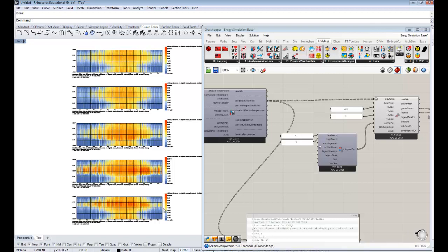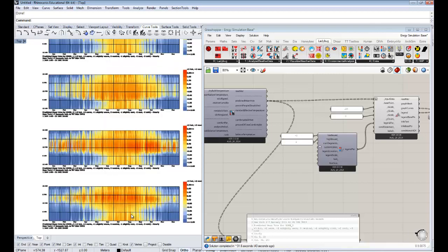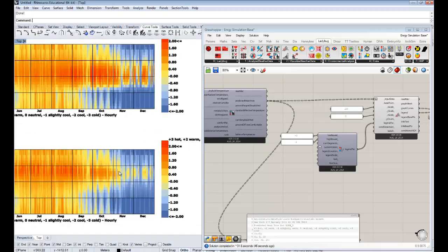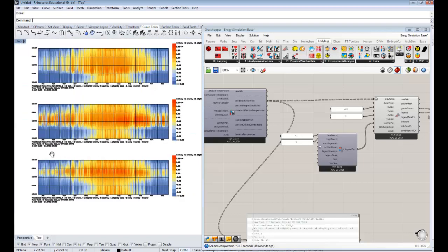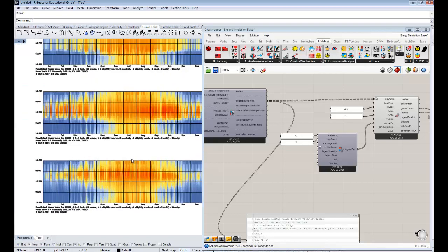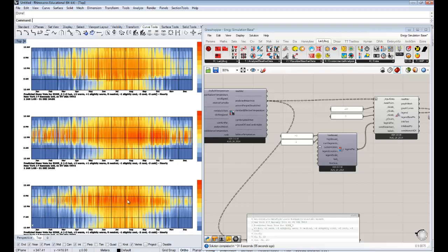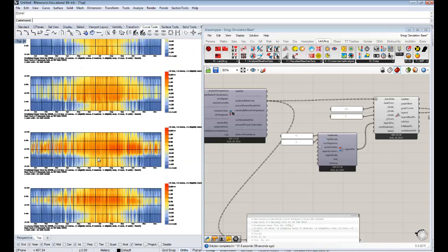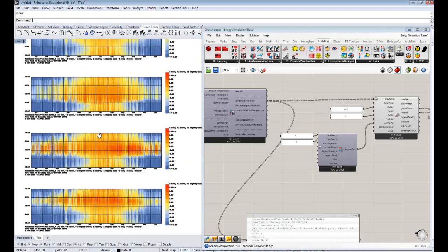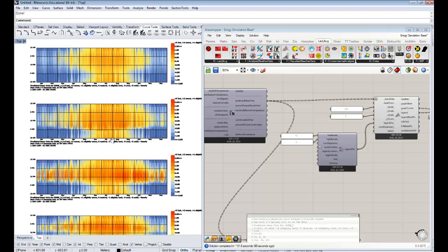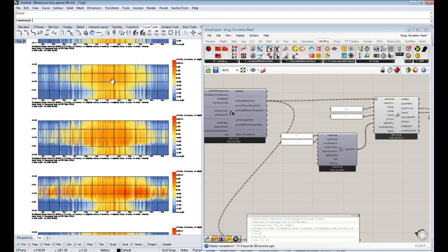But you can also see certain opportunities, or problems that might start to arise. The red color here means that these zones are getting too hot in the summer, which are specifically our south zones, and it looks like our west zone. So this must be our south zone, and this is our west zone, which is getting that direct sun in the afternoon after 6 p.m. So you can really start to piece through this and understand the potentials of what's going on. And you see, okay, but the north side is really comfortable at that time, so that should work.